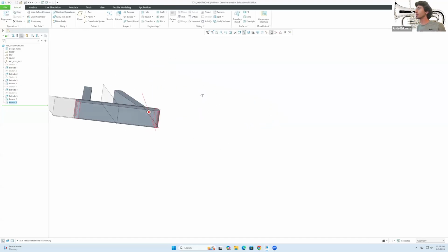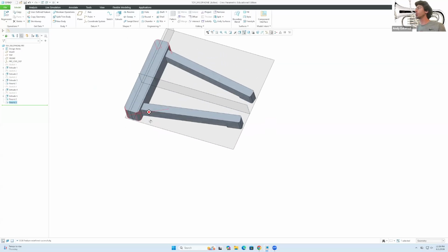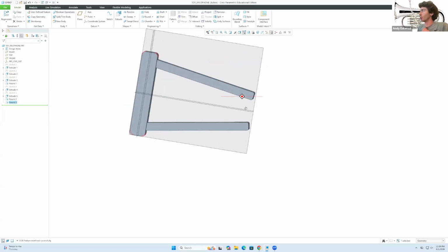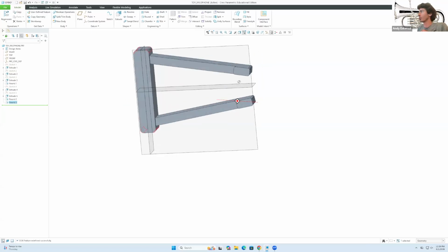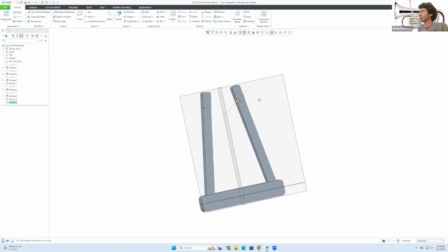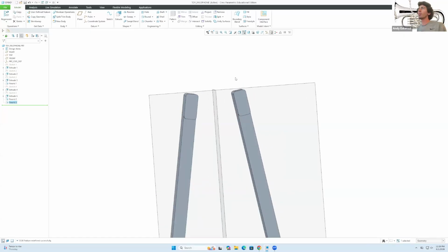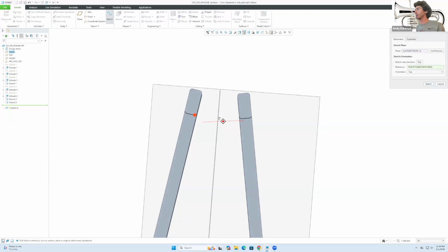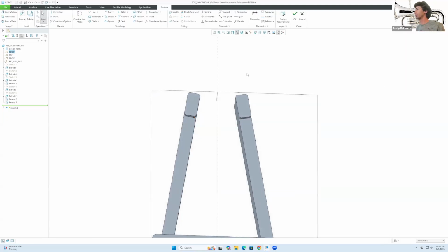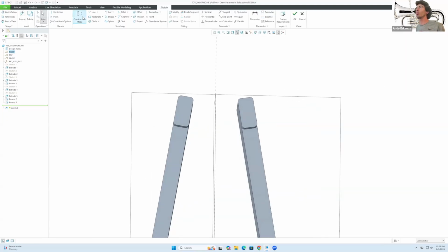Good. So now this is moving along pretty nicely overall. Then perhaps the one thing that we could try to do is like a little connection in here between the 2 blocks. So how could you do that? Well, actually, it's not too difficult. What I would do is go here to sketch, and I select that face in here, go here to sketch, and now I'm gonna do a construction line that will be between that point and that point, escape.